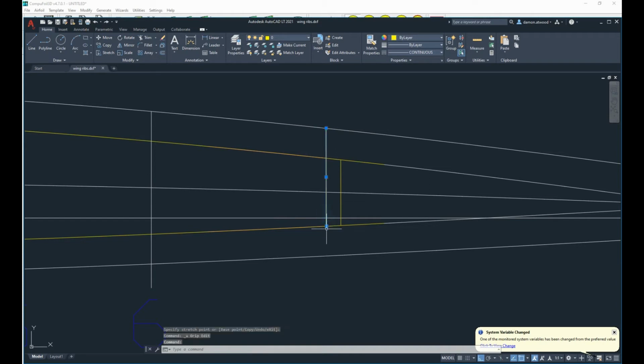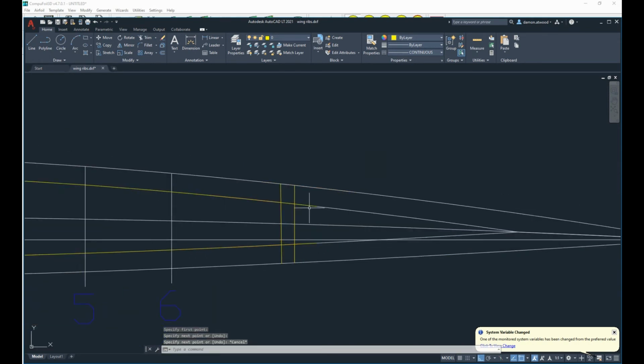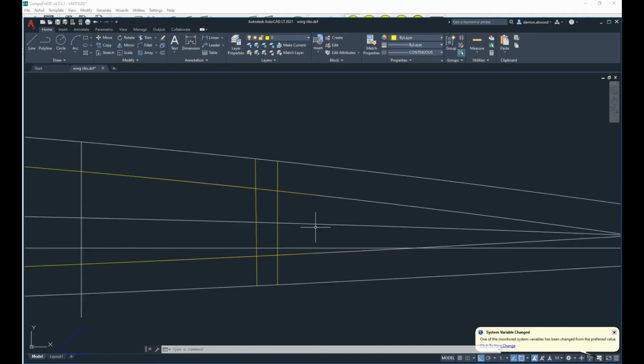And I'll measure that in a minute to make it an 1/8 inch. But right now I'm just doing some reference lines. So the laser cut part he wants is going to be this shape right here, but we've got to be able to put the radius in there for the aileron. Okay, and this is the thickness of it. So what we're going to do now is grab a 2-point circle, and I am going to drag the 2-point circle out until it touches or is damn close to it.